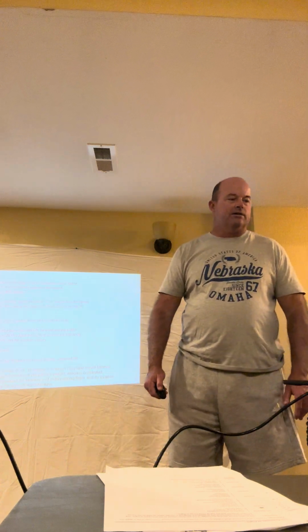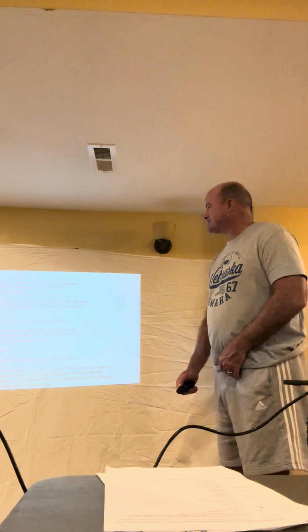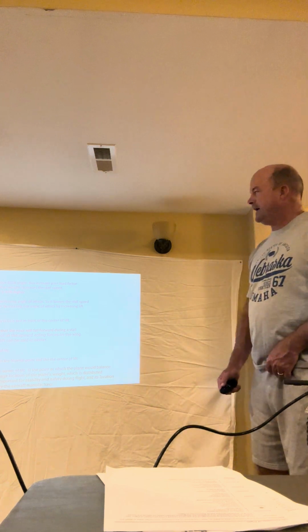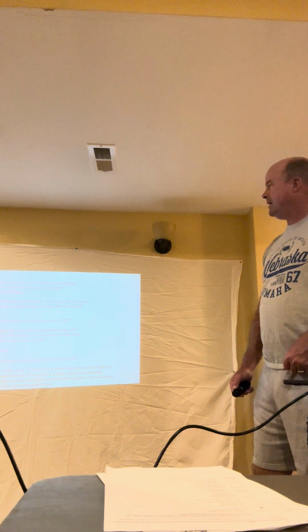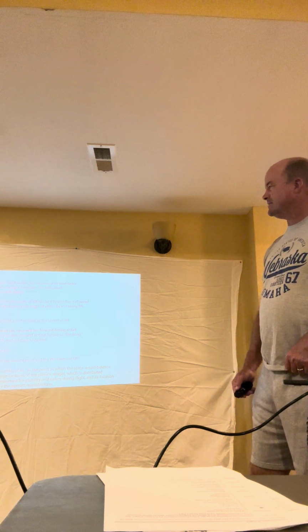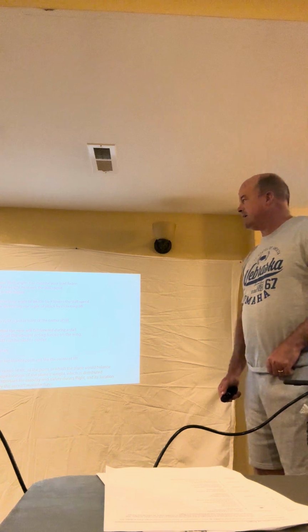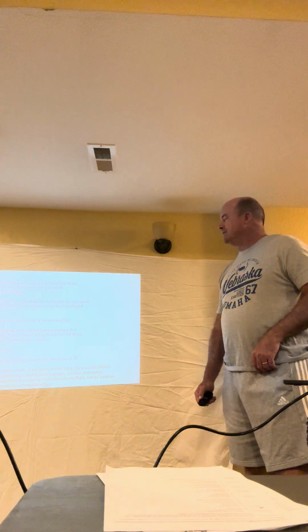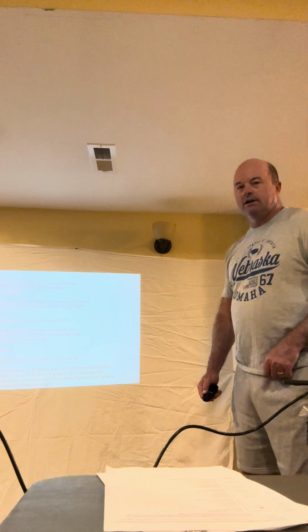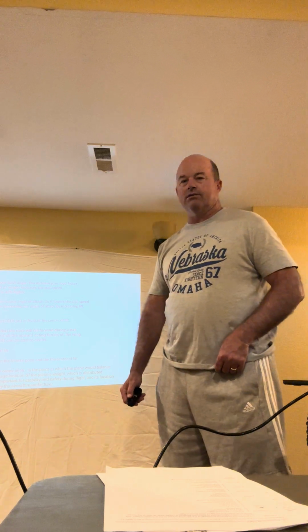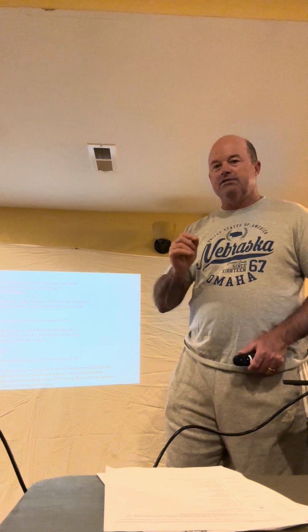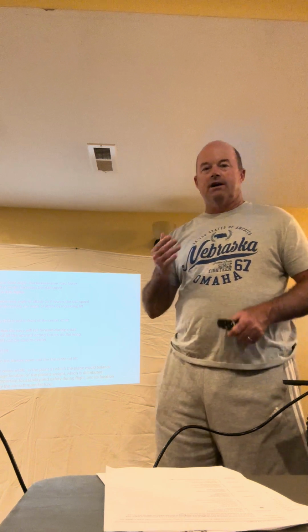All right, I want to talk a little bit about bank angle. When you increase your bank angle, you increase your load factor. Load and weight increase the stall speed. So at a 60-degree bank, the stall speed is 42% higher in a 182 and in general, right? So you've got to be super careful, right? You're flying along at a normal speed, and then all of a sudden you just decide you want to bank real quick, turn real sharp, right?